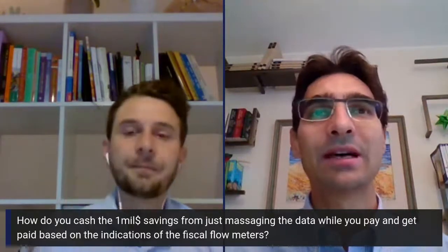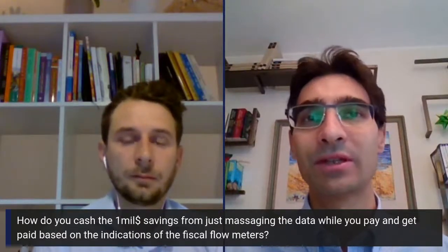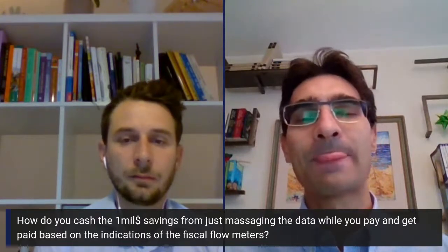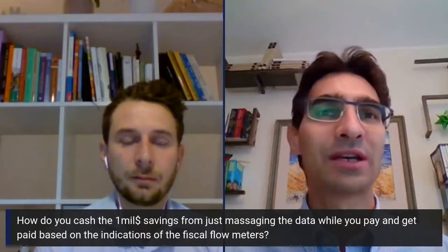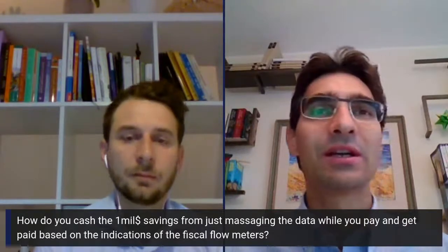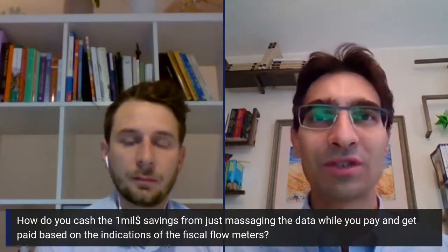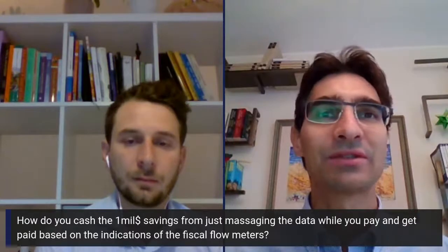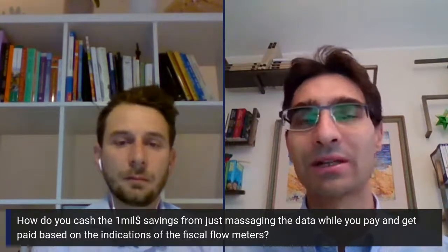The weights are correlated to the tolerance of the instrumentation. So when you declare something as fiscal, the tolerance is set to 0. In a loss reporting, you are able to not set this to 0, but of course, typically, custody transfers, fiscal flow meters have a very tight tolerance, so they are quite accurate.